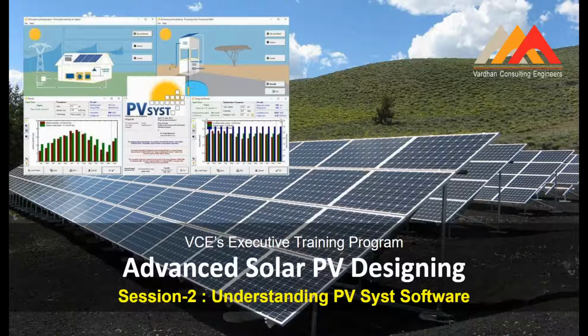So if the VOC of all the series connected modules crosses 1000 volt, it is not good for designing. It should be less. So that's why the number of modules connected should be about 22, 24, 16, 18. It depends upon the model.